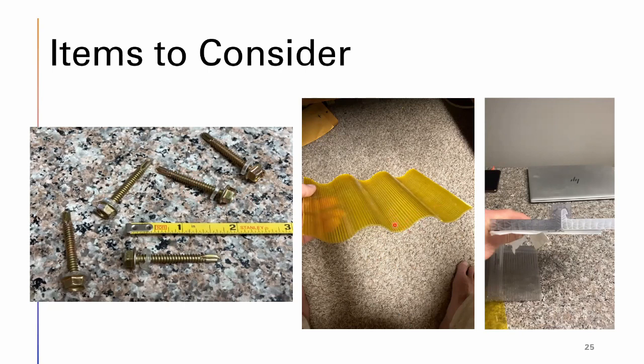I have some clear corrugated. This is a 2-layer corrugated. Corrugated is really easy to install. It has good resistance to bending, but it can handle a 12-foot radius. That's what it's rated for. But it has an air gap.